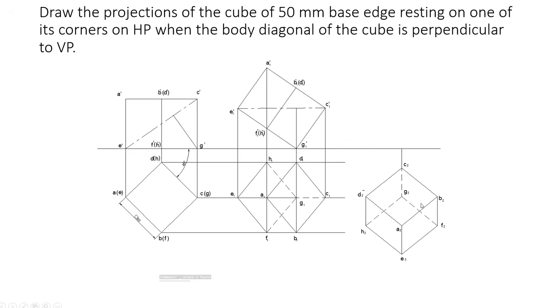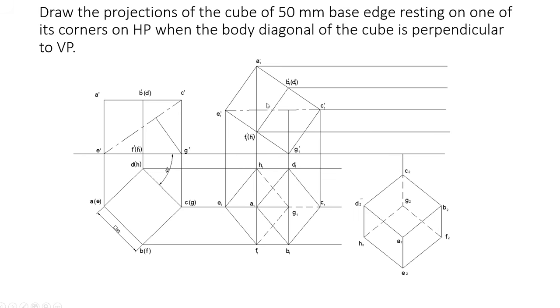So now you have copied this diagram here in such a way that this line is perpendicular like this. Now you want to draw the projection lines from here like this. From all these points you draw projection lines. You have 4 lines, projection lines, including this base you have 5 projection lines. This point and this point will be a common point, so you have only 1 line.